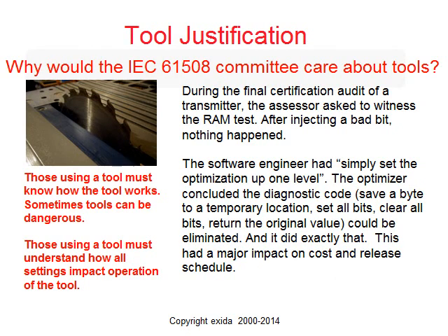And to point out why this matters, this is a real-life example about the impact of a tool. A company had made quite a few SIL-rated products. They were using the same compiler. During the final audit for certification, a RAM test was implemented. Nothing happened. A bad bit was injected. Nothing happened. The diagnostics didn't see it.